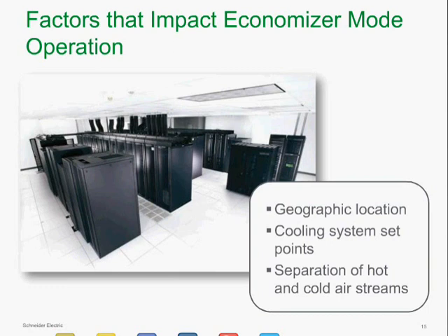We're seeing more facilities that are really pushing up towards the ASHRAE recommended guideline for inlet air temp, which is 81 degrees Fahrenheit. But I think if we use 75 as, say, a basis, that avails much more dramatic use of economizers based on the outdoor ambient conditions versus running your set points down in the 65, 68 Fahrenheit degree range. And then the last thing is containment.